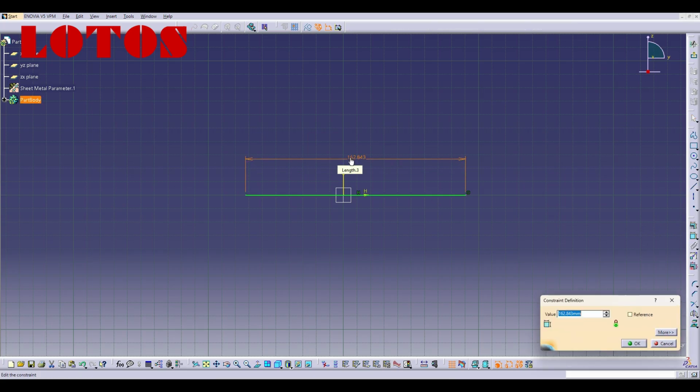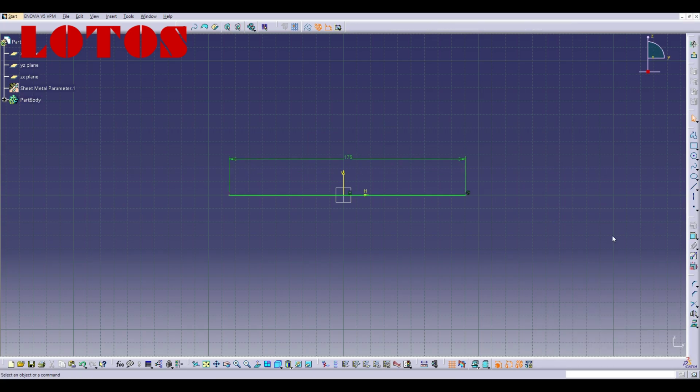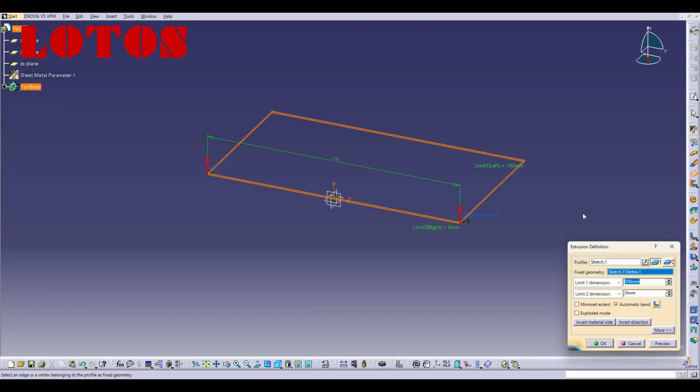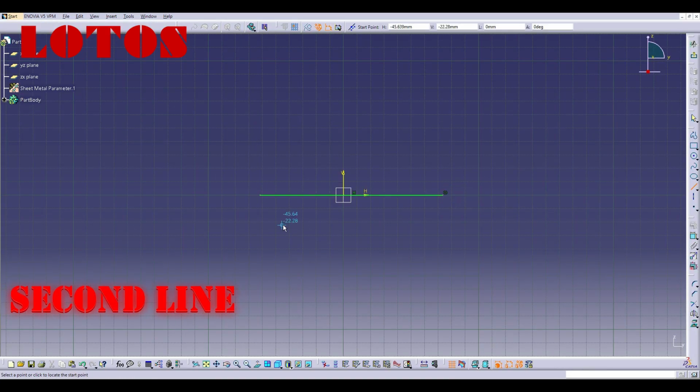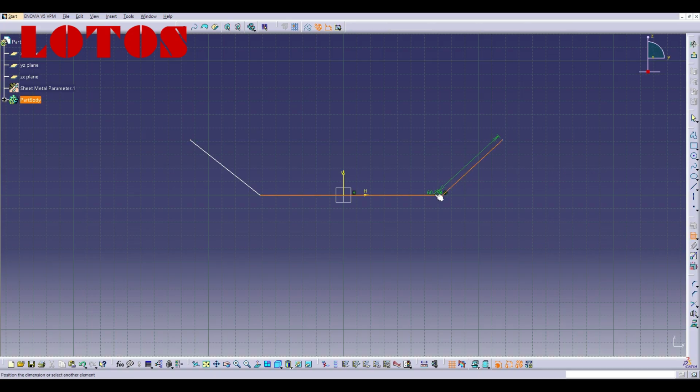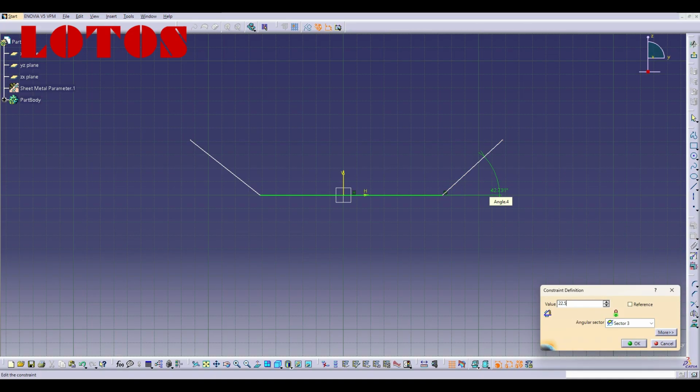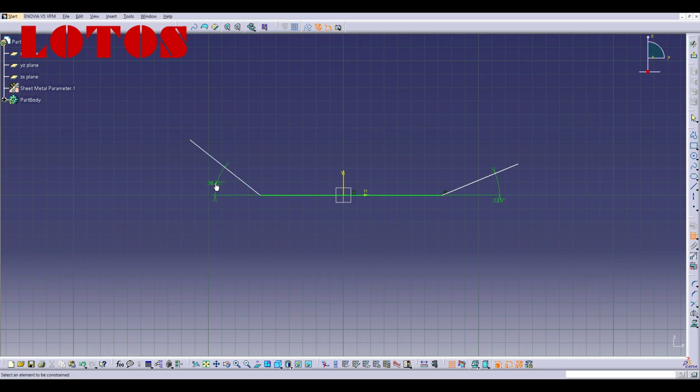It is important to note that this forming operation includes two 90-degree bends, which we divide into 4 steps, with each step bending the sheet by 20.5 degrees. However, our machine requires 6 stations, 1 for feeding the sheet, 4 stations for bending operations, and a final station to apply an additional 5-degree bend to compensate for the springback and ensure that the angles reach a true 90 degrees.